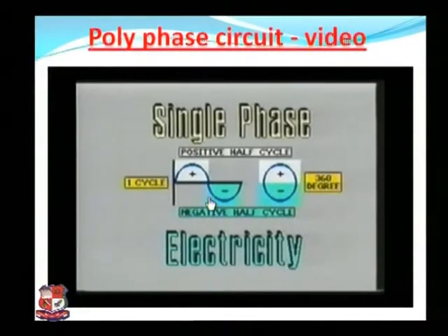As you can see from this simple illustration, the current flows in one direction for one alternation, and then flows in the opposite direction for the second alternation. Also notice that the voltage potential constantly changes value as the sine wave goes from 0 to maximum positive peak and back to 0, then from 0 to maximum negative peak and back to 0 again to complete one cycle.